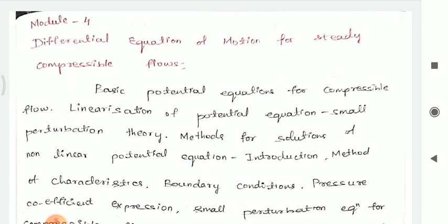And then we have studied module 2, everything about normal shock waves, what happens to the flow properties downstream of the normal shock wave, what are upstream properties and downstream of normal shock wave properties, and then what happens to the ratio of flow properties like static pressure ratio P2 by P1 in terms of upstream Mach number M1, rho 2 by rho 1 in terms of upstream Mach number M1, T2 by T1 static temperature, and then stagnation pressure ratios like P02 by P01, and then change in entropy ratio, that is S2 minus S1 in terms of upstream Mach number M1.